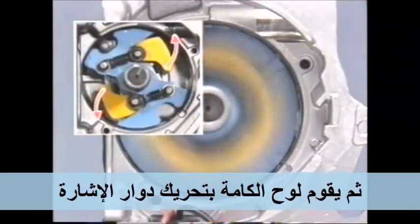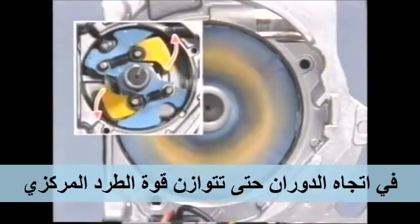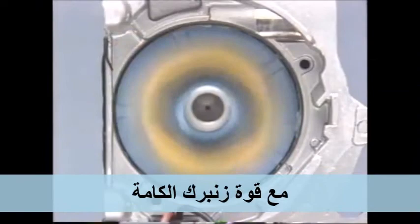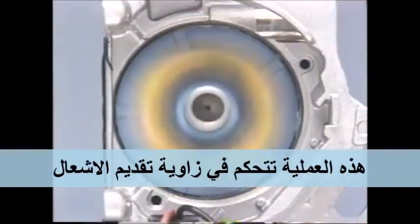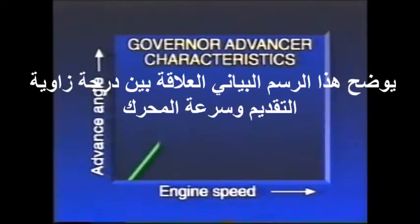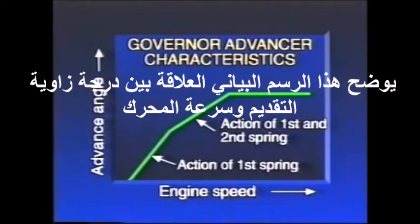Then the cam plate moves the signal rotor in the direction of rotation until the centrifugal force balances the spring force. This operation controls the advance angle. This graph shows the relationship between the degree of the advance angle and the engine speed.